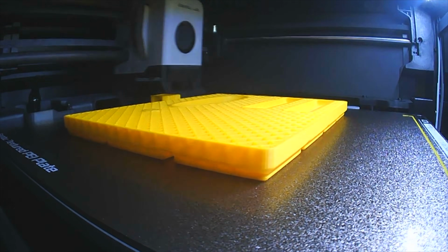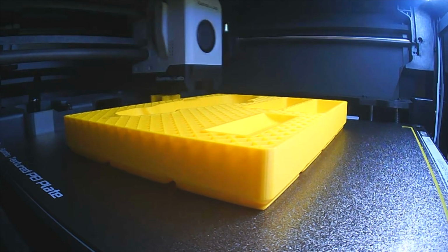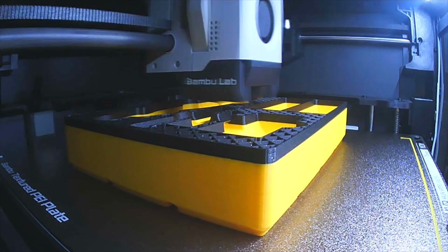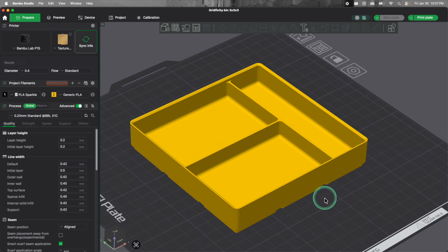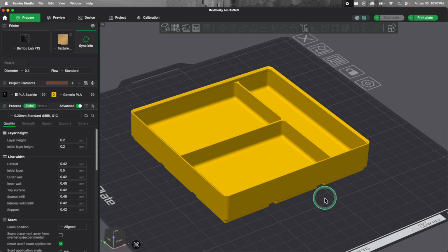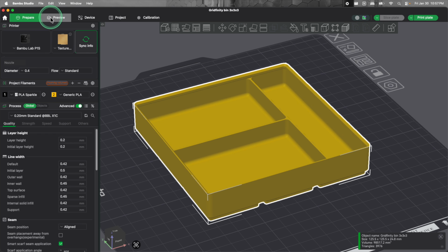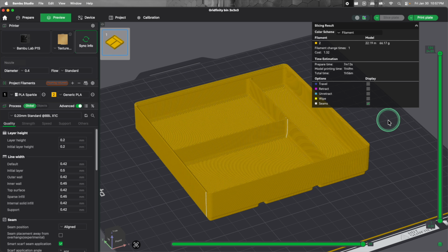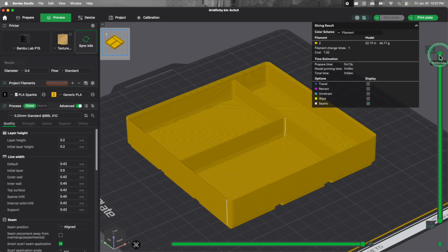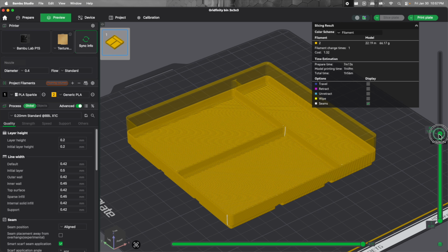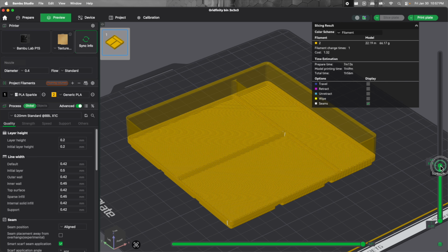Now, option 2 is getting into multicolored printing using your 3D printer slicing software in a couple different ways. The way I found myself preferring to do it was to just set my printer to swap colors after a certain height. This not only will save you from wasting too much material using color swaps, but it also works if your printer is only equipped with single color printing. In your slicer, you can drag your slider on the right-hand side of the screen down to your desired color swap range, then right-click and select color change.